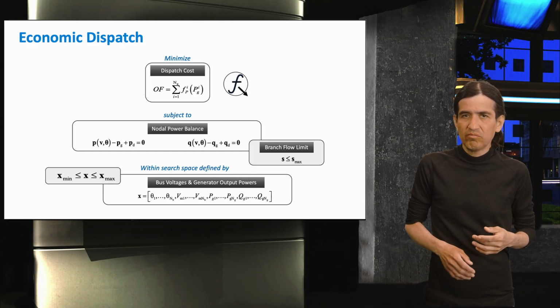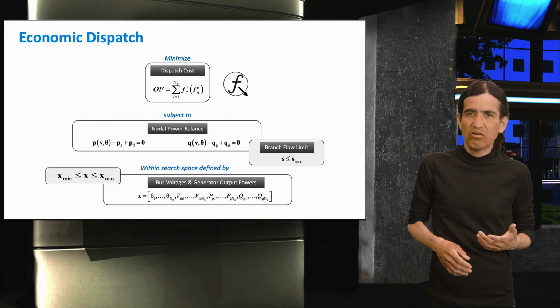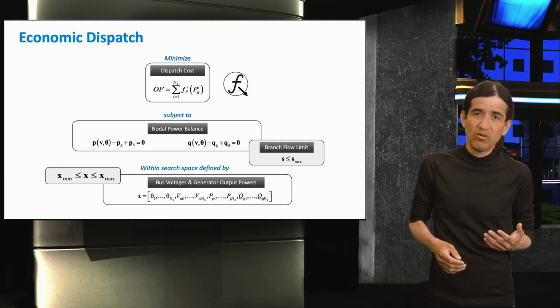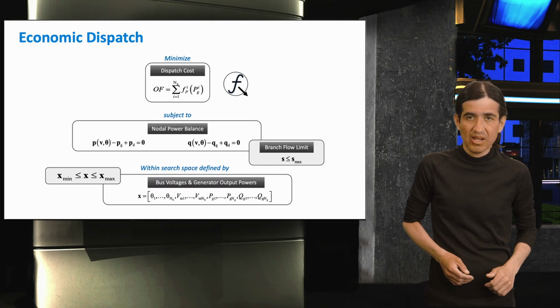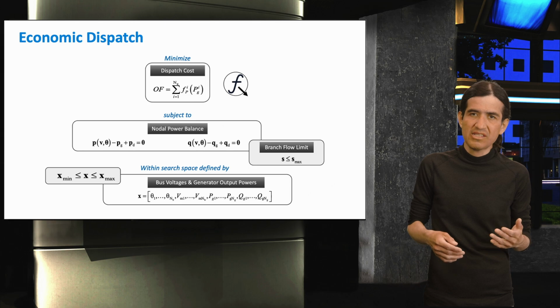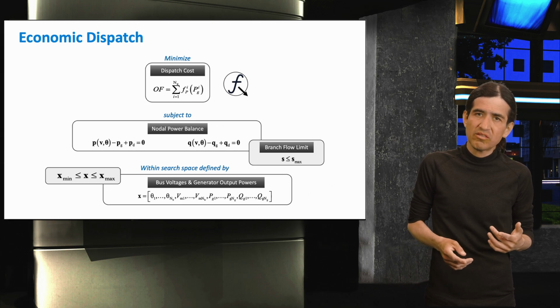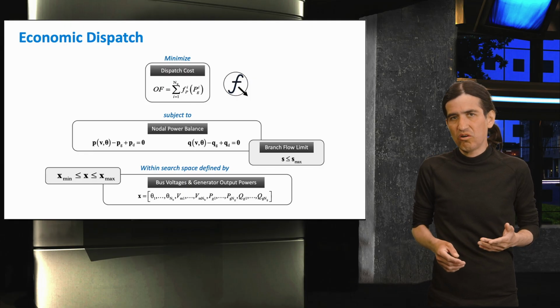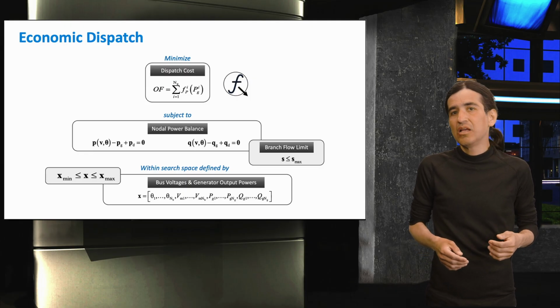The solution vector consists primarily of the active power outputs of generators and, in extended formulations, possibly voltages or reserves, and set points of controllable assets, which are adjusted to find the least cost operating point that satisfies all constraints.